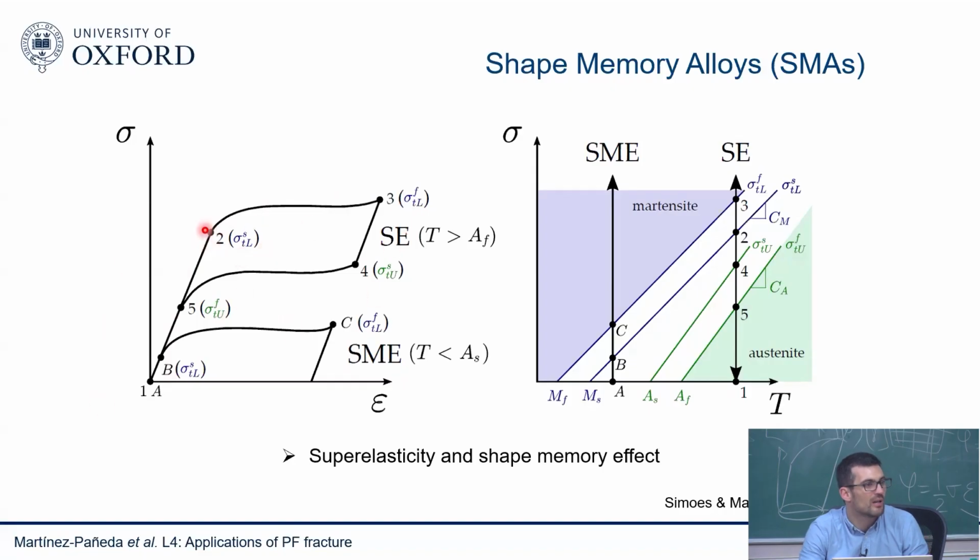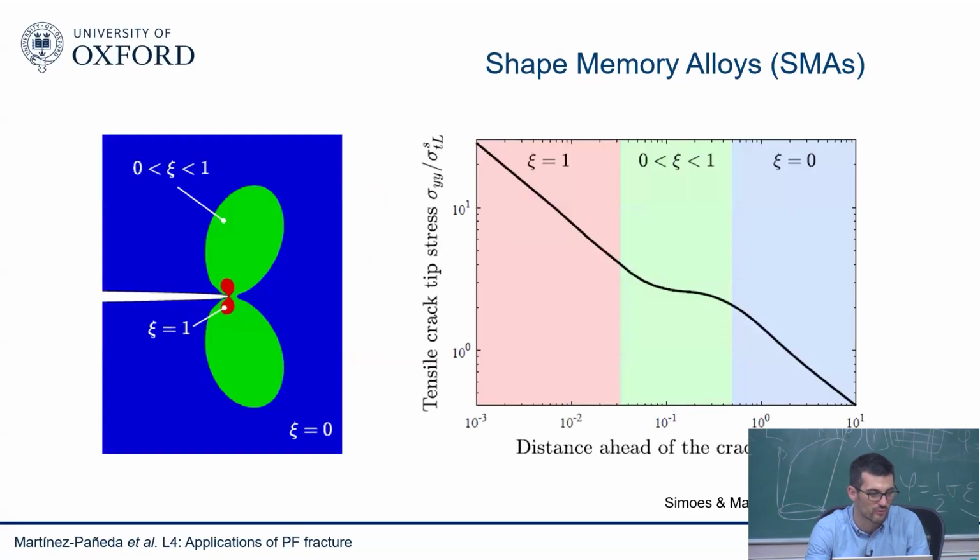You need to tell the model at what temperatures and what stresses this phase transformation happens. So you input those parameters into the model, then eventually you reach that point, and you trigger the beginning of that phase transformation. Based on your constitutive choices, you define how fast this phase transformation happens, slowly, like you're hardening in a way, and then eventually when you come back and so on. So that's what drives the evolution of this variable.